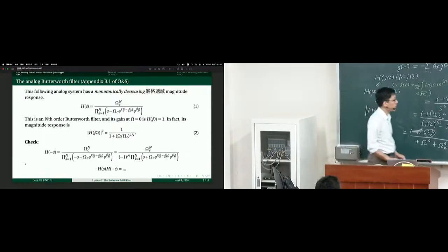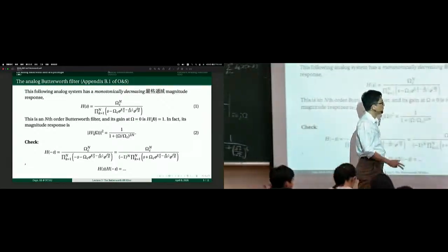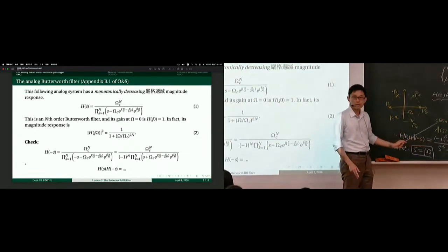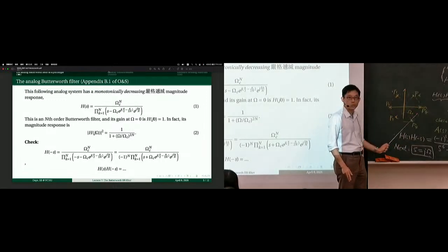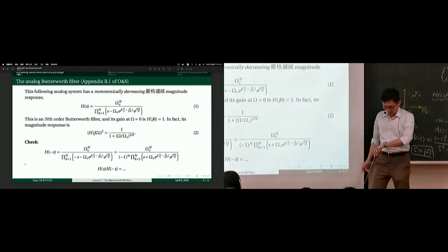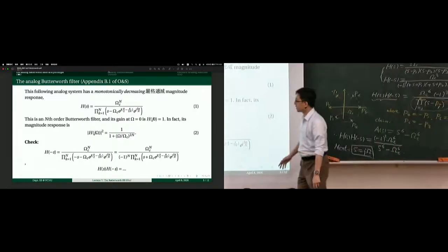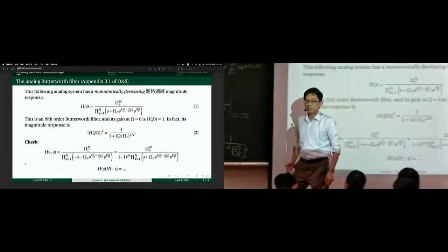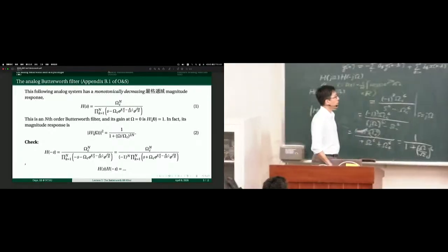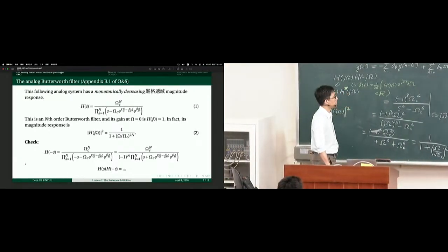If we have 6 roots like that, if we recap, we have 6 roots like that, the only polynomial that has exactly these 6 roots is this polynomial. That's the key step. So that's a derivation of the Butterworth filter prototype and the magnitude response square.